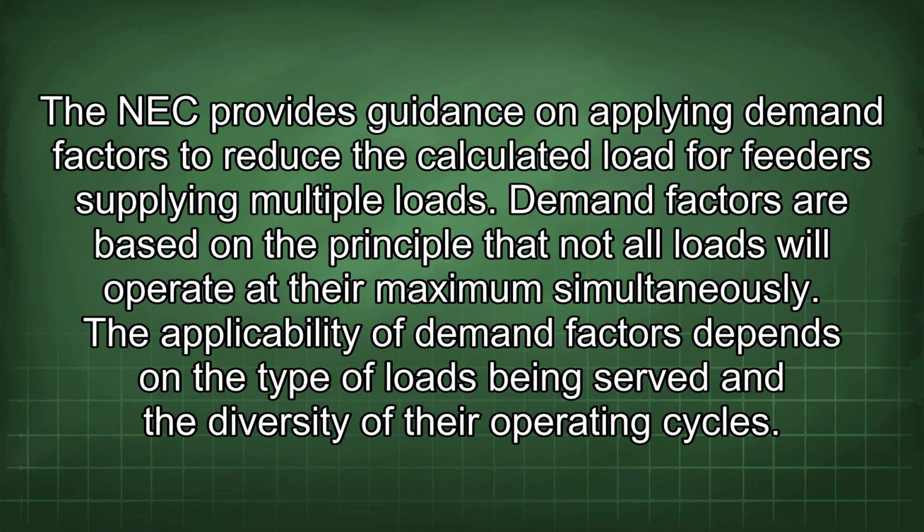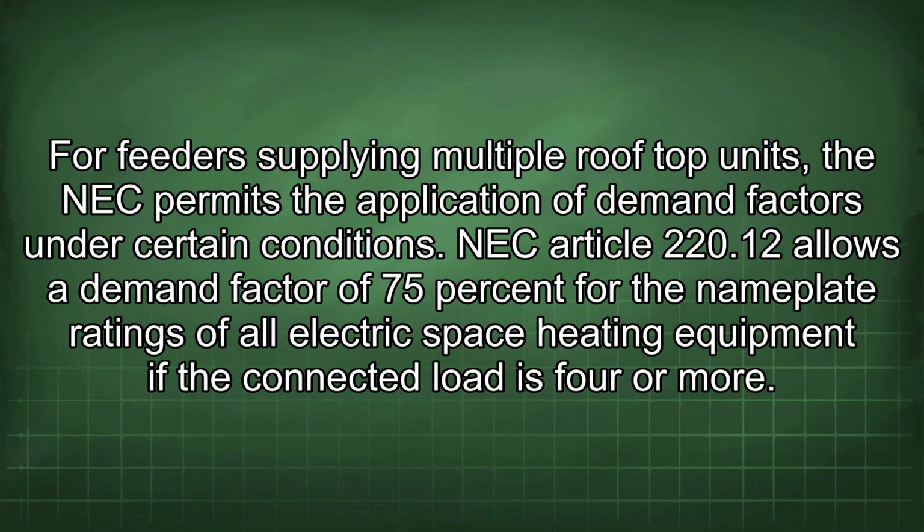The NEC provides guidance on applying demand factors to reduce the calculated load for feeders supplying multiple loads. Demand factors are based on the principle that not all loads will operate at their maximum simultaneously. The applicability of demand factors depends on the type of loads being served and the diversity of their operating cycles. For feeders supplying multiple rooftop units, the NEC permits the application of demand factors under certain conditions.